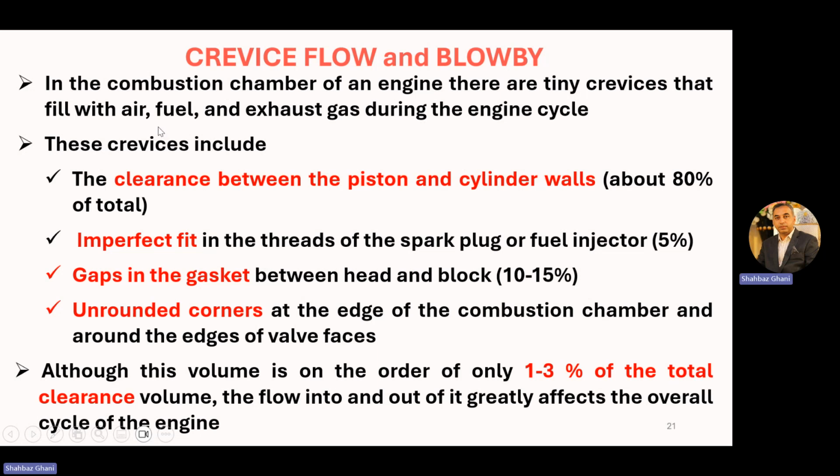Now, the next part after the combustion is the crevice flow and the blowby. In the combustion chamber of an engine, there are tiny crevices. The crevices are gaps that fill with air, fuel, and exhaust gases during the engine cycle. These crevices include the clearance between the piston and the cylinder walls, about 80% of the total.